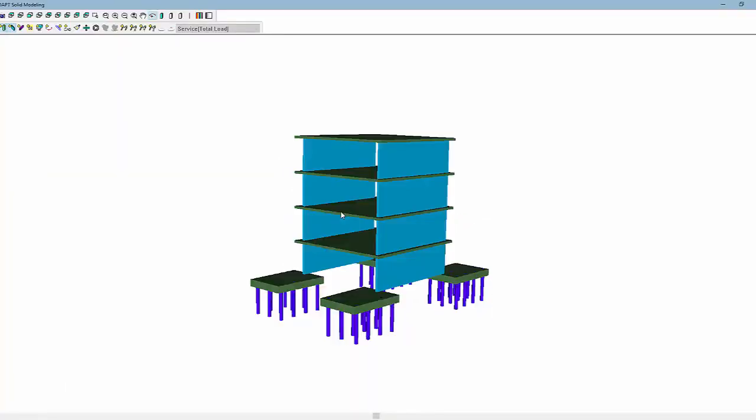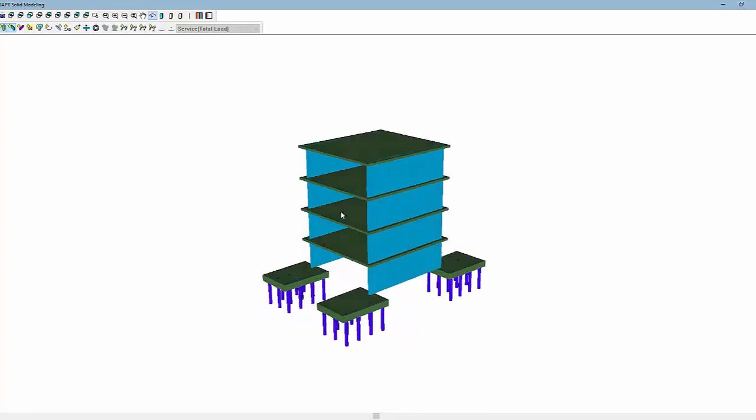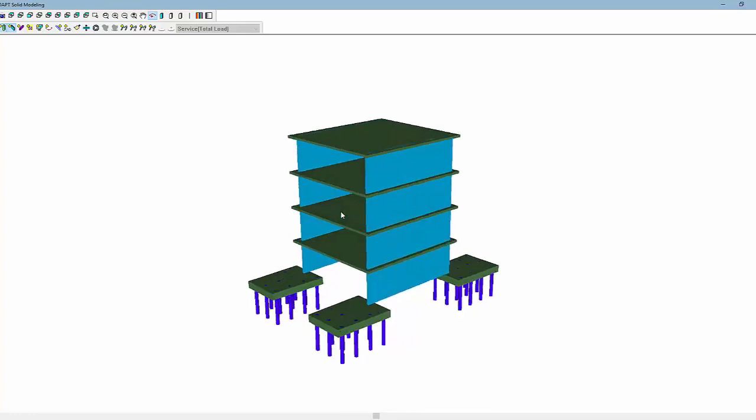Now the goal here would be potentially to design these walls as beams, which is not really doable with how the program uses design sections over components. So analytically we can obtain a solution here, but if I go and replace these with beams, which is what I'll show you, we have a stability problem because the beam gets referenced off of the plane that it belongs to.